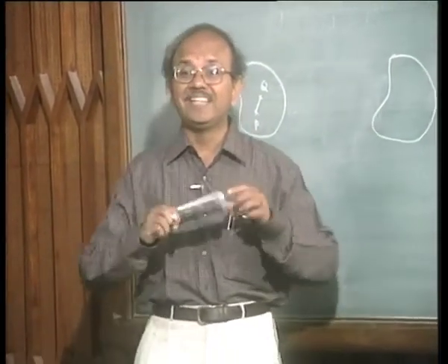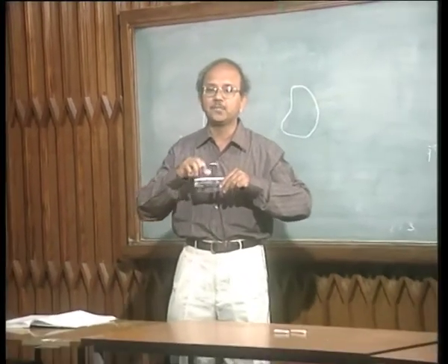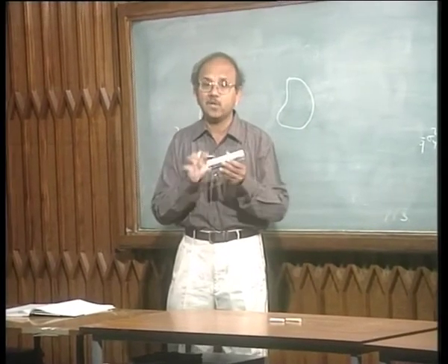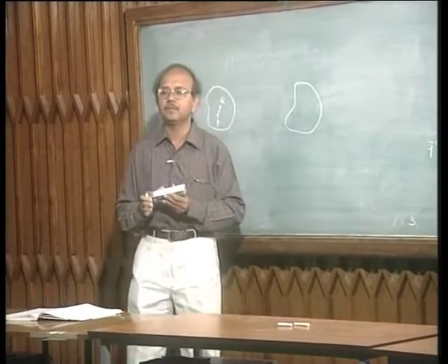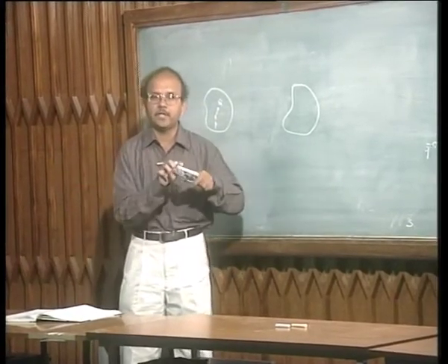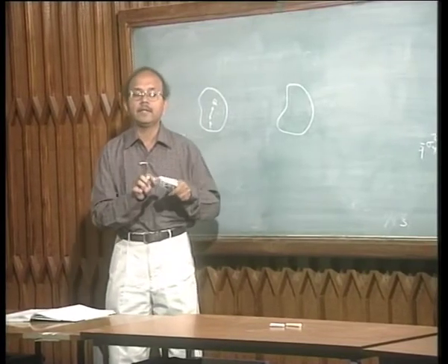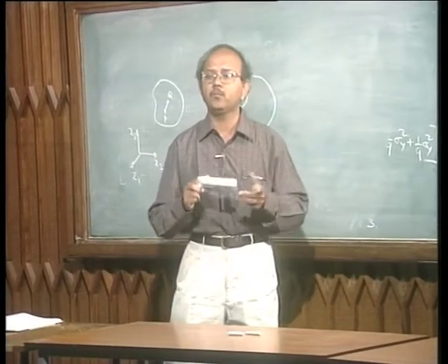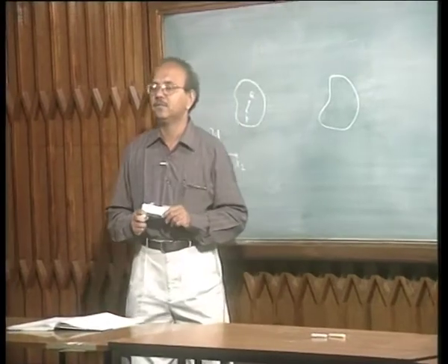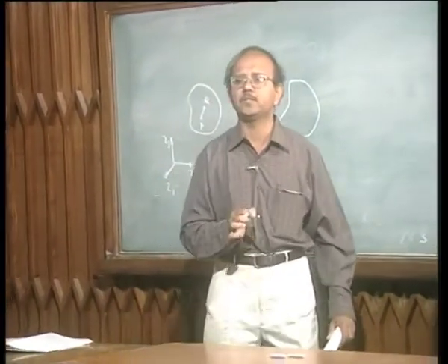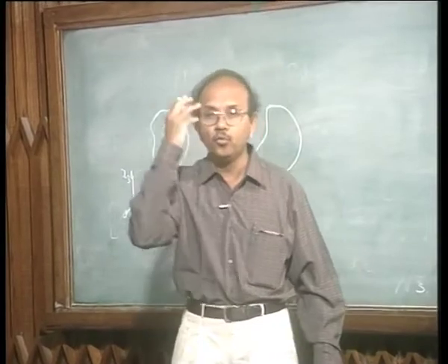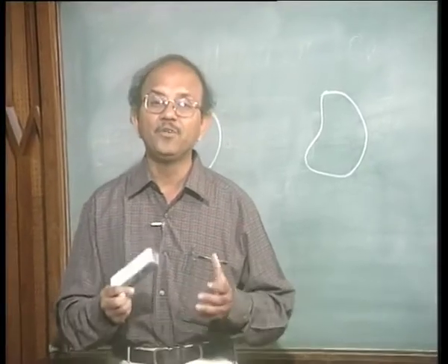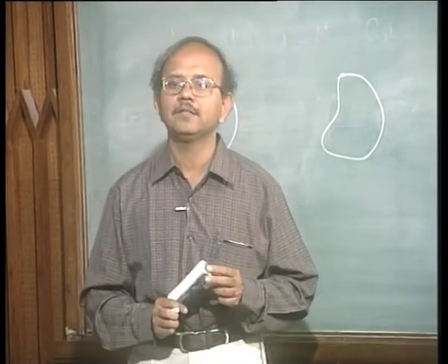Yeah, in other words, there is a relative displacement, or in other words, the displacements are not uniform throughout the material particles of the body. Yes, they are also displaced from one position to another position, right? When I pull it, there are some particles which have moved, right? But the movement of these particles may not be uniform. When I do all sorts of things to this duster, the movement of these particles is not uniform. So this non-uniformity of displacement is what you would have intuitively called deformation. It's deformed. Okay? And we know that this is what causes strain.